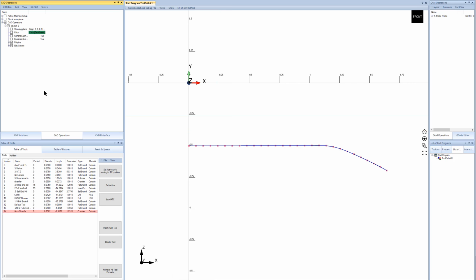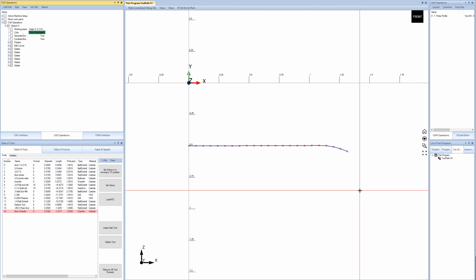So for this, the goal of this video is we're going to take this angle right here, this straight section, and we're going to change the angle of it. So maybe 1 or 2 degrees so we can change the shape of the piston. So I'm actually going to remove some of this. I'm just going to take all these points here that kind of make a straight line and just remove some of them, maybe like that. So we still kind of get that arc shape. And this is really mostly a straight line on the top, but the arc is what we want to keep in there.